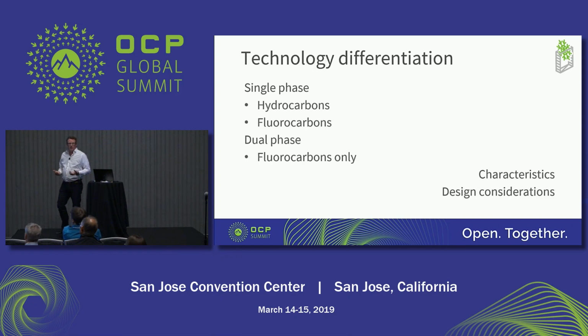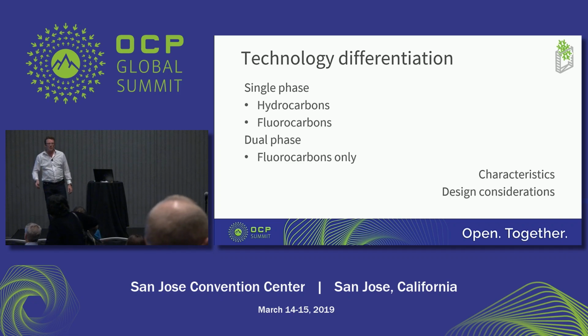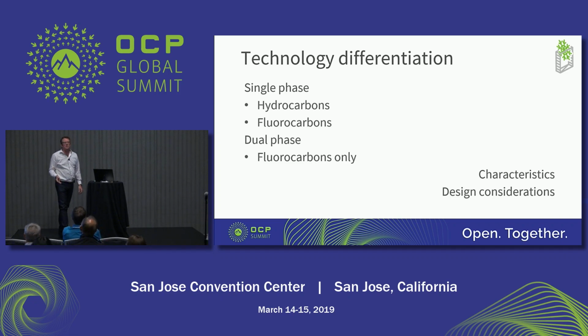And the first thing that we're addressing is to define the different types of technologies that are out there. You've just seen Alibaba with a great solution that they've spent many years on developing. And they've done a terrific job. They're doing a lot of things right, if not all the things. But it's categorized as one of the flavors of immersion. So first of all, the liquids are divided between hydrocarbons and fluorocarbons. Hydrocarbons are oils, whether they're synthetic or based on mineral oils. And fluorocarbons are used in single or dual phase situations. They're highly engineered.